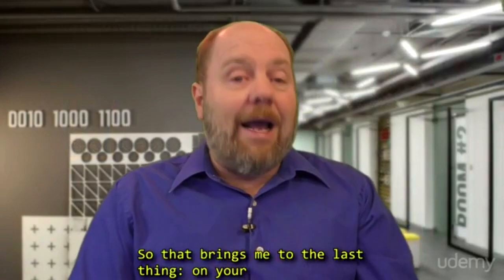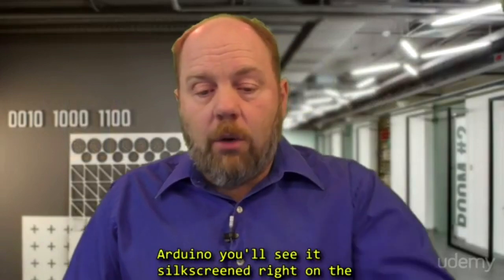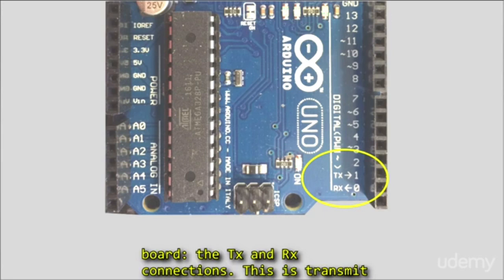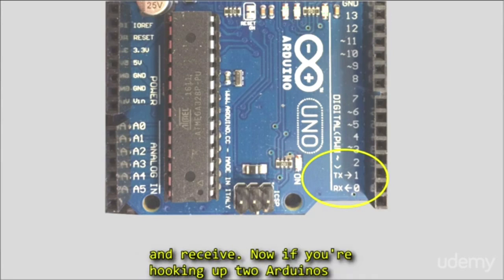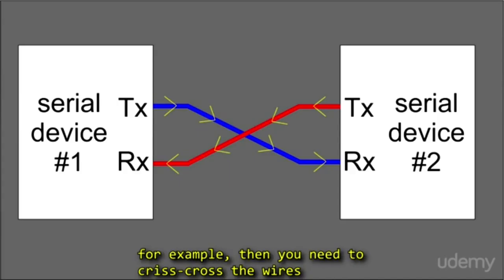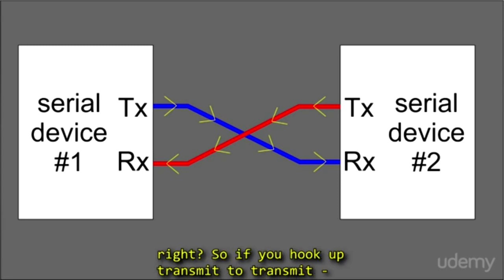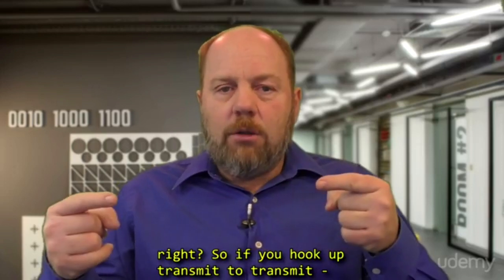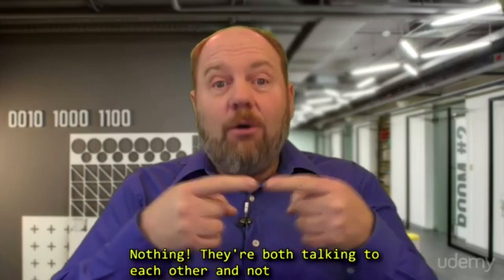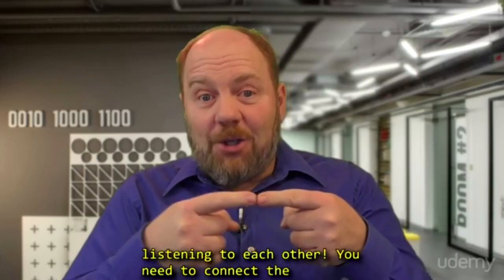So that brings me to the last thing. On your Arduino, you'll see it silkscreened right on the board, the TX and RX connections. This is transmit and receive. Now, if you're hooking up two Arduinos, for example, then you need to crisscross the wires here. Transmission is output, receiving is input, right? So if you hook up transmit to transmit, what do you get? Nothing. They're both talking to each other and not listening to each other.